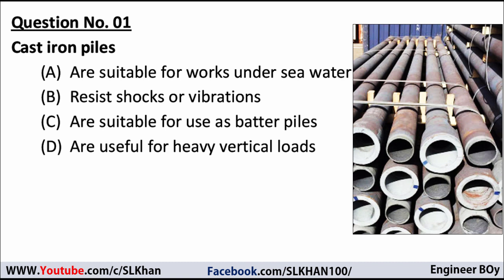Option A, are suitable for works under seawater. Nope, these are not suitable to work under seawater. However, these can be used but not suitable, because in the seawater, when you drive a pile, there can be a lateral force powered by the seawater in horizontal form, which creates tension on the cast iron piles. And cast iron piles cannot take tension. That's why I'm going to say option A is not okay over here. I'm not satisfied with that.